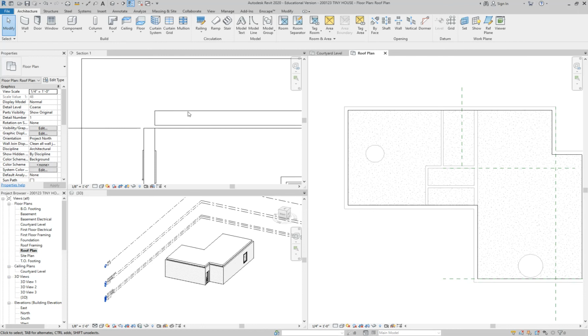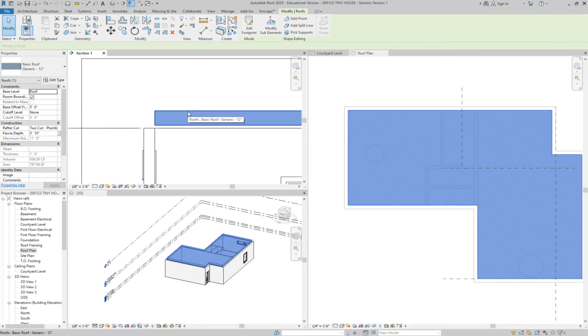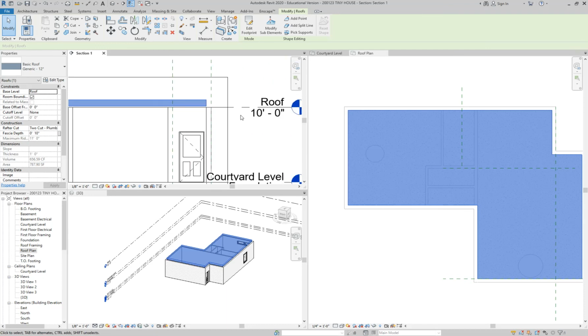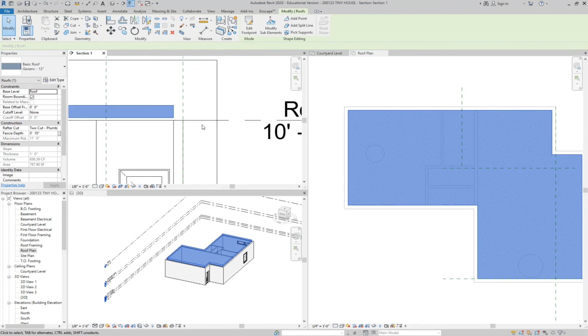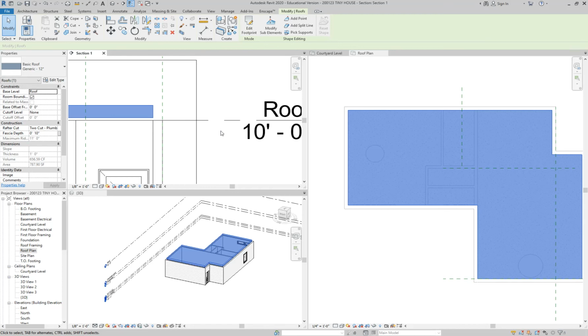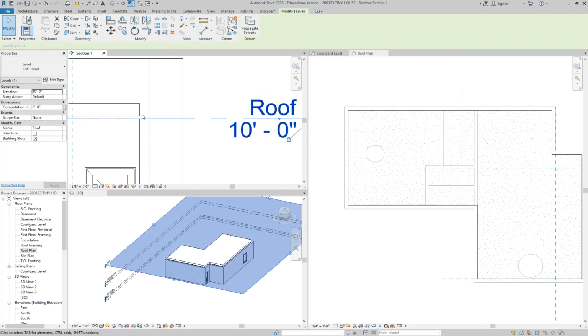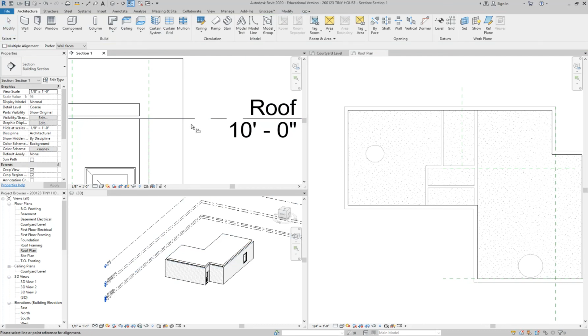But here, this is where I will just say that Revit is wrong because it says it's on the base level roof. Is it actually on the base level roof? Is Naima going to waste time figuring out what's wrong? No. To move on, I'm going to use the align command. So what is the correct place? Here, right? And this is what I want to move. So I'm going to do align. I'm going to say, this is where I want you to go. This is what I want to move. And now it's right.